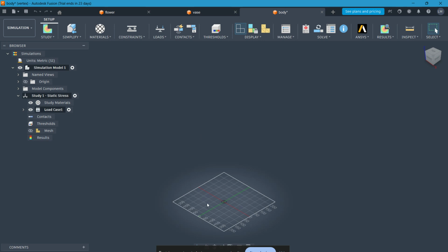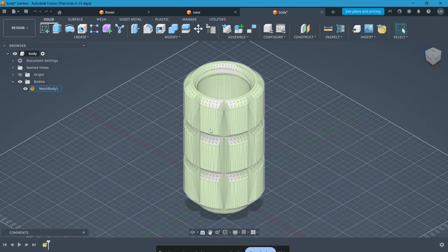Finally, if nothing else works, rebuild the problematic geometry. This might sound extreme, but deleting and recreating a feature can often eliminate hidden issues that are causing the failure. Quick tip to remember, phase solid meshing errors almost always mean your geometry is either invalid or too complex. Fix the geometry and the mesh will usually follow.